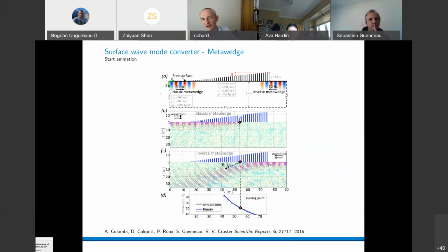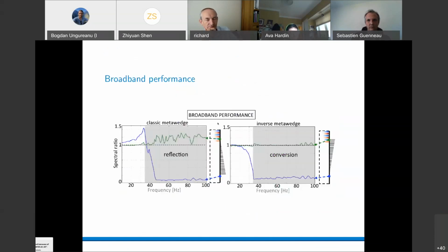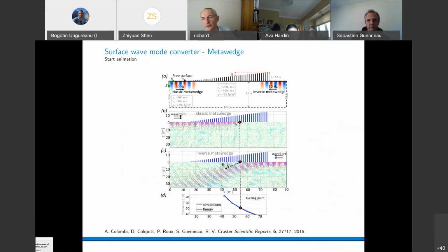And so we could use the insight from our model problem to help us design for this graded problem. We can obviously grade in two ways. We can send waves from short to high, or from high to low. If we send them from short to high, the wave slows down, and eventually stops. Why would we care about that? Different frequencies would stop at different places, so we would have a frequency selecting surface. And when a particular frequency stopped at a particular resonator, it would stay there for quite a long time, and it would feed energy into the resonator, and you'd hope to get large amplitudes.